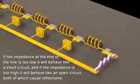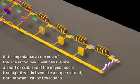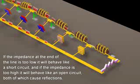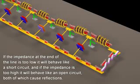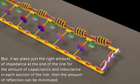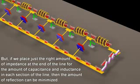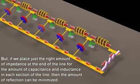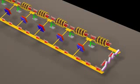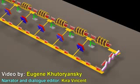If the impedance at the end of the line is too low, it will behave like a short circuit. And if the impedance is too high, it will behave like an open circuit, both of which cause reflections. But if we place just the right amount of impedance at the end of the line for the amount of capacitance and inductance in each section of the line, then the amount of reflection can be minimized. Reducing reflections is desirable, as reflections can significantly interfere with the proper operation of a circuit.